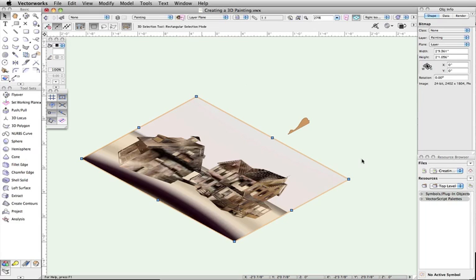To create the picture frame, we will use the Extrude Along Path command. Here, I have already brought in a profile from the Copper Beech Millwork resource file, available with Vectorworks Architect or Designer. You can also draw a profile using the Polyline tool.